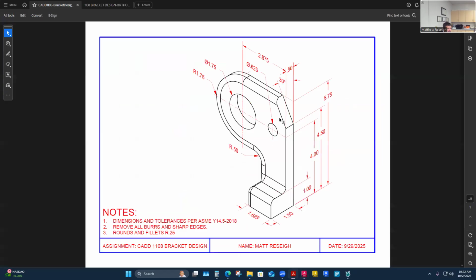I know that it's missing a dimension, which I'm going to add today. That 0.88 should have been added. But what I want to do is go back, and if the engineer, or whoever the design intent came from, explicitly had dimensions, I'm going to maintain those. I don't want to round those off. And I have rounded some here.